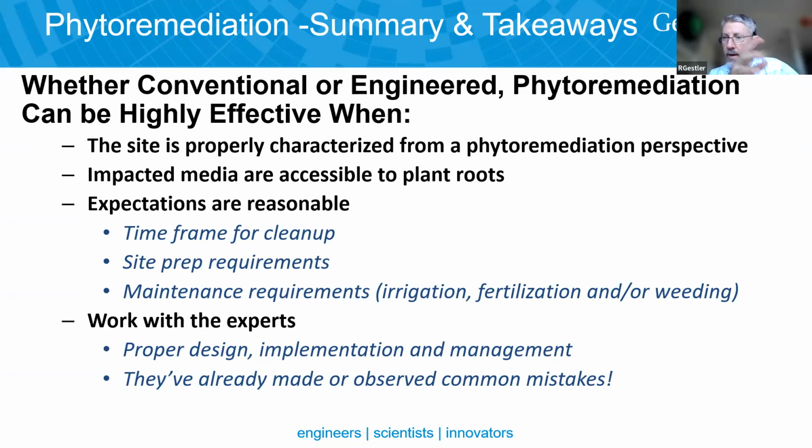Whether we're applying conventional, that is traditional phytosystems, or engineered approaches, phytoremediation can be very effective when you properly characterize the site from a phytoremediation perspective, when your impacted media, whether that be soil or groundwater or both, are accessible to plant roots, and where your expectations are reasonable for all stakeholders, including regulators and clients, which accounts for the time frame to meet your cleanup.